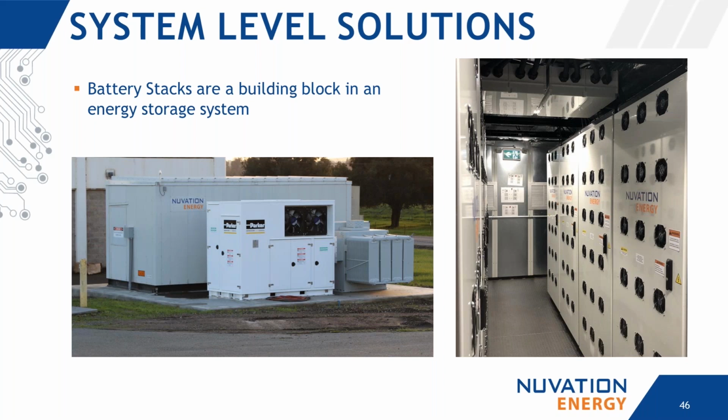In the images shown, we designed a containerized solution capable of providing up to 2 megawatts of power for our 15-minute profile. The energy stored was just under 600 kilowatt hours, and the system was composed of 20 battery stacks, with batteries capable of discharging up to 4C. In this case, this was very much a power application, and one of the toughest challenges encountered was dealing with the thermal management of the system.